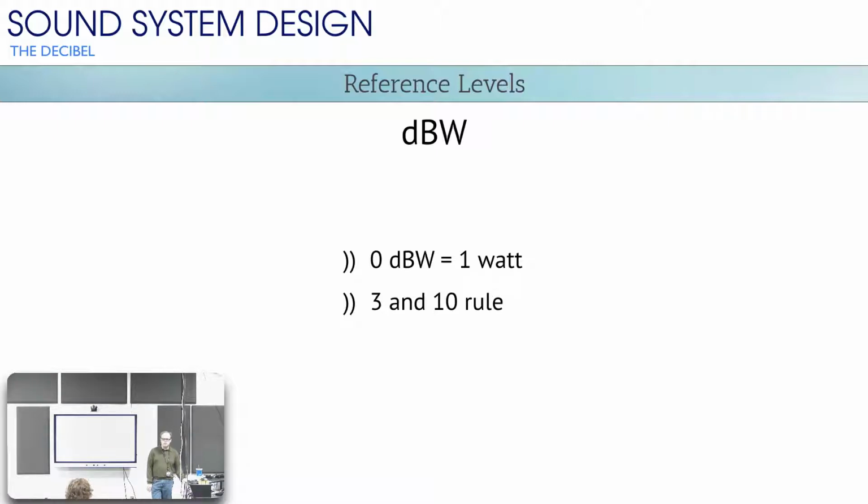That does not turn into sound. You know, there's no direct equivalency to the number of watts and the amount of sound that generates. There's no direct connection, because there's a device in between called the loudspeaker driver, and each loudspeaker driver is going to do a very different thing with that same amount of power. You could put 100 watts into one loudspeaker and only get 60 dB SPL. You could put that same 100 watts into another loudspeaker and get 100 dB SPL. And that's a huge difference. So the watts are not particularly relevant in and of themselves.